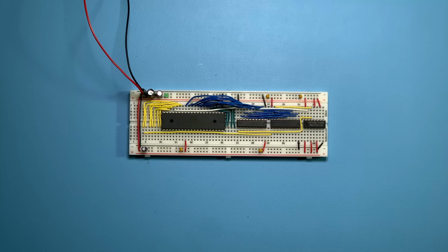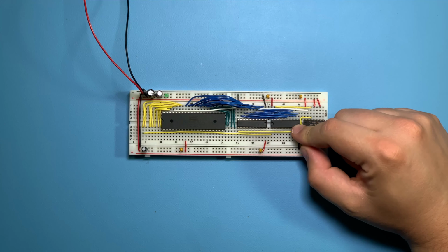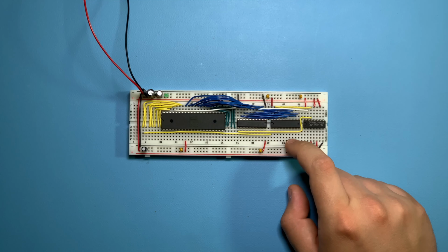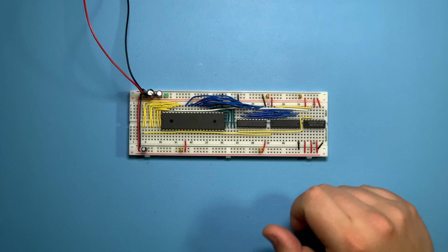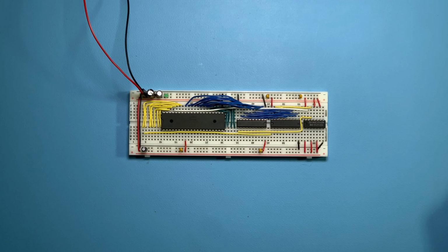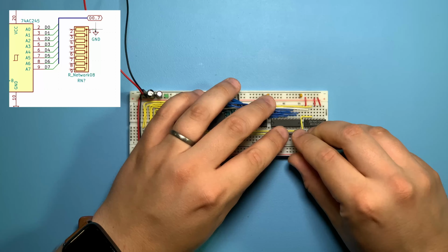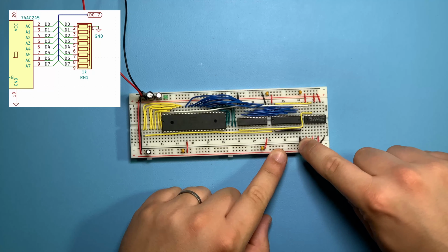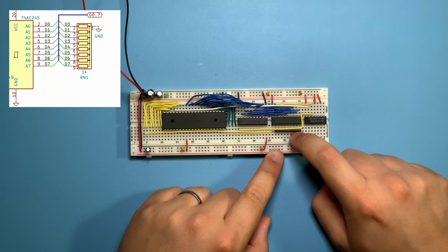There are actually two improvements that I've thought about doing to the datasheet circuit. The first one is, since we're only activating the bus transceiver on the second half of the clock cycle, its outputs are going to be floating during the first part of the clock cycle. And since all our circuit is going to be CMOS chips, we really don't want any floating pins. So I'm going to add pull-down resistors to all of the outputs from the transceiver. This is a 1K resistor array, and we can pretty conveniently plug it here to have all the outputs pulled down through the ground pin here. So that when the chip is not driving the outputs on the first half of the clock cycle, they're going to be pulled down to 0 by this resistor.